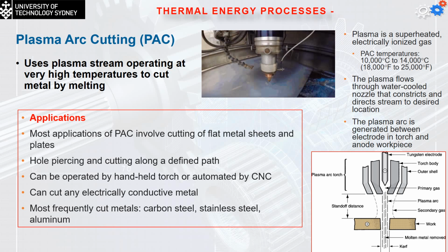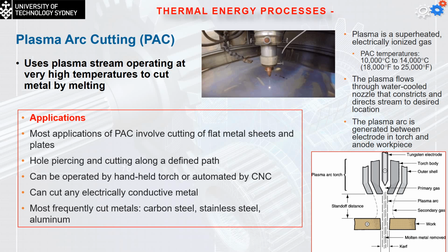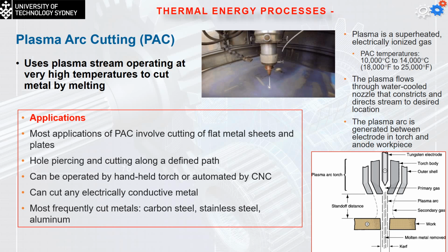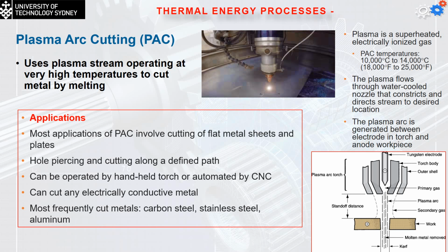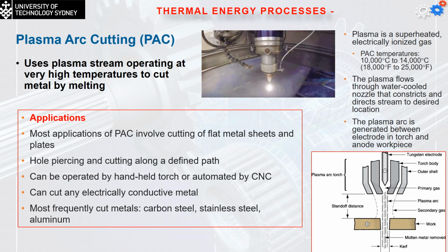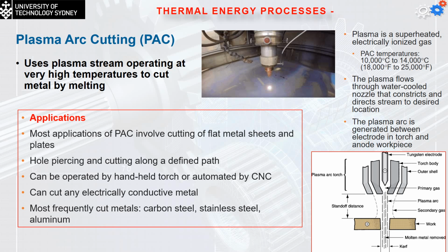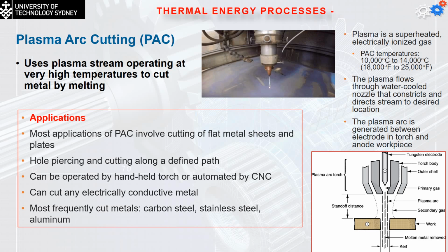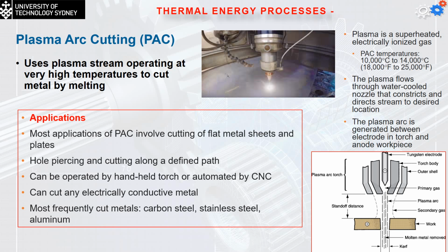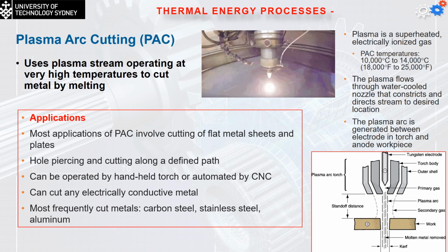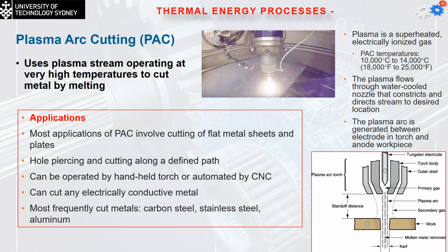Now, once again, it's not a perfect operation. The temperature is so high that it can cut highly reflective surfaces. But the problem is, it can damage the surface. That's why they cut under water, just to reduce the heat affected zone. Number two, a laser cutter can cut plastic, for example. This one will damage the part, just melt it.